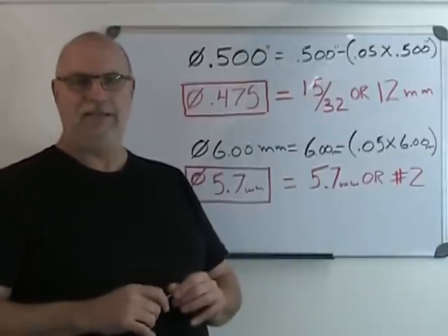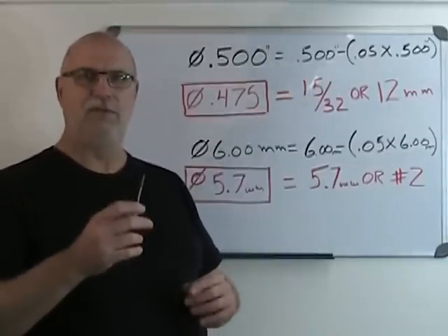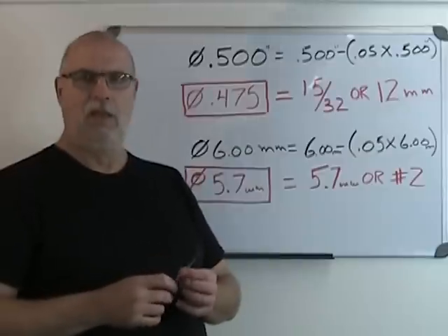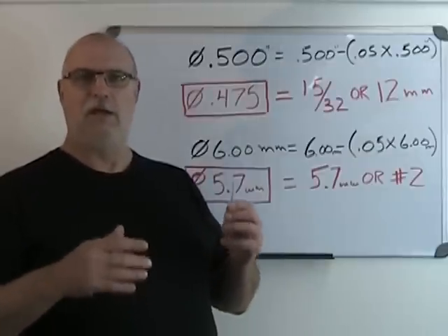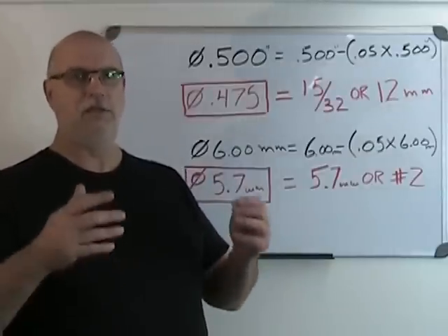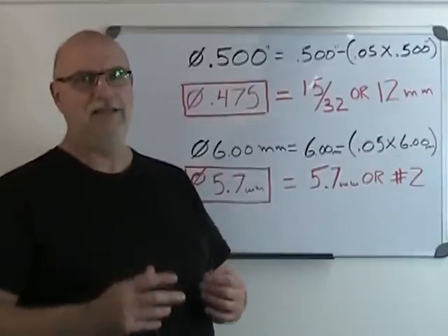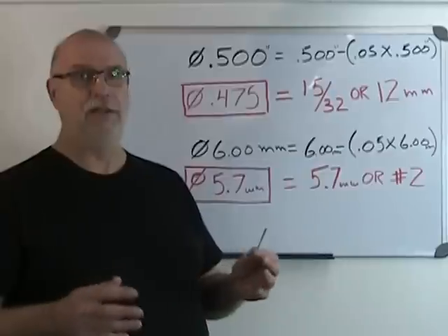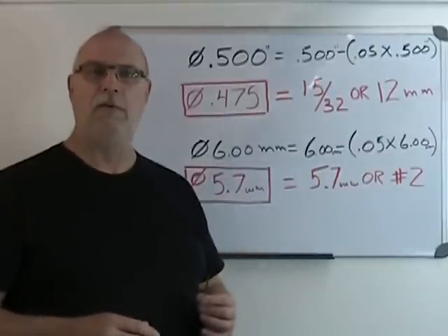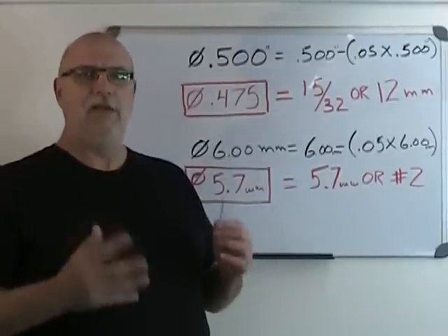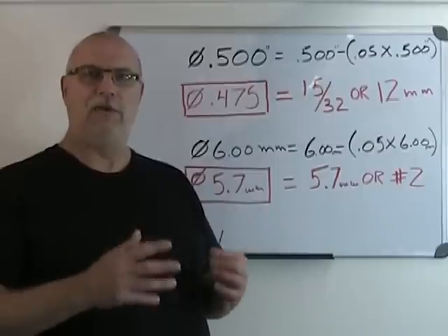Well, that makes using reamers really interesting, because obviously a preferred dimension that's a hole-based dimension would be easily attained with reamers. I mean, that's basically what they're made for. But I can't use them when the hole has to be accurately positioned.